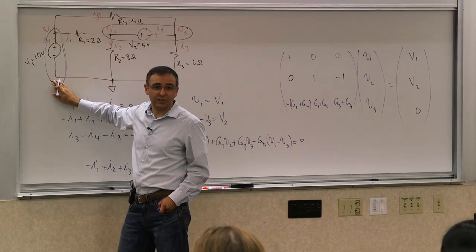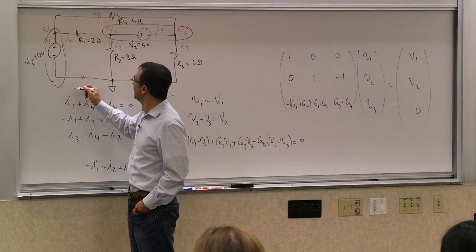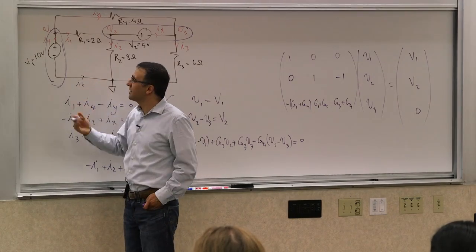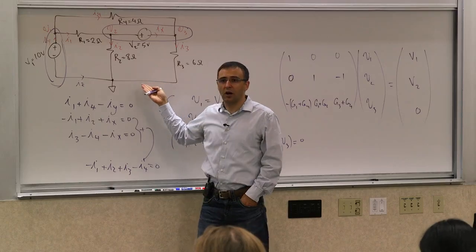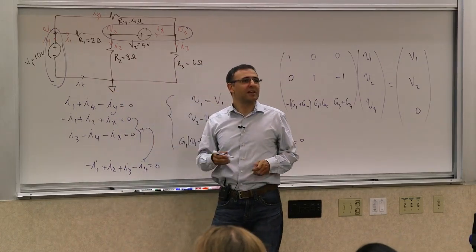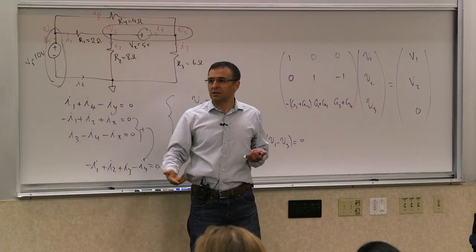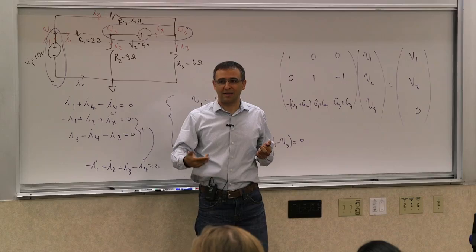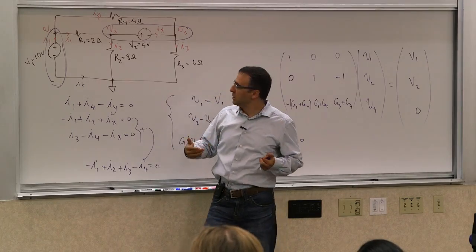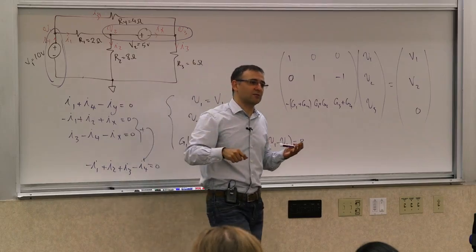Since one end of it is connected to ground, you don't need to worry about it. You could define this new current, whatever, IZ, and write it in terms of that, but then you're adding one additional unknown to deal with through this node. And you've eliminated the advantage of using a ground, a reference. The ground eliminates one equation; it reduces the order of the system by 1. So yes, you can do it and solve it, but you have basically thrown that advantage away.